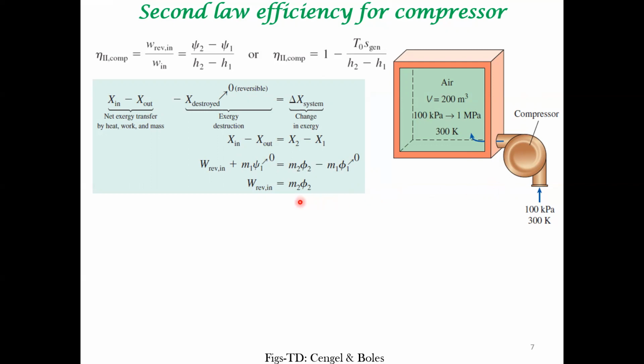So the work done is this term, and this other term is zero because the inlet fluid is at a dead state. It is in equilibrium with the external atmosphere. Therefore, this term is zero.